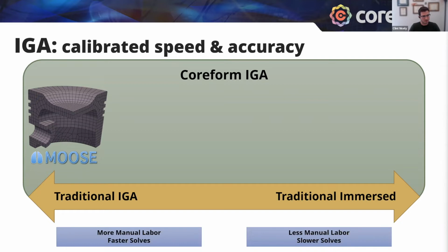it's been idealized here. Some of these things have been simplified because in a body fit mesh, you still need to simplify things in order to get it to be meshable with hexes.